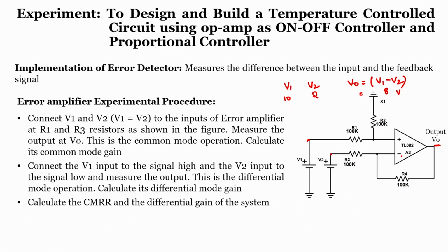Now, this one I am taking 8, this is 4. So V out will be 8 minus 4, 4 volt. Then 6, 6. I will go with 8; in this case, I should get minus 2 volt, right, and with 4 and 10 I should get minus 6 volt. Let me see whether I get these values if I design it in a practical system.